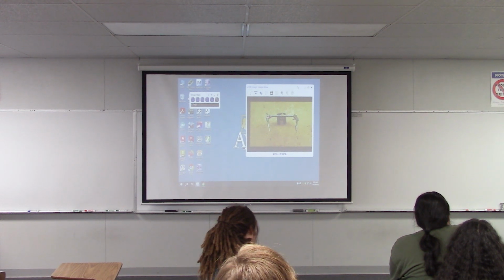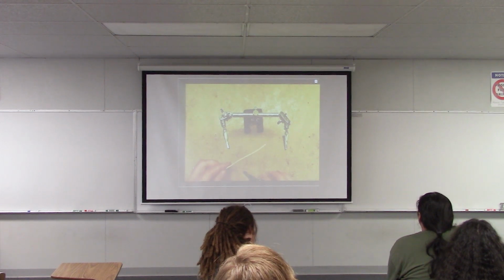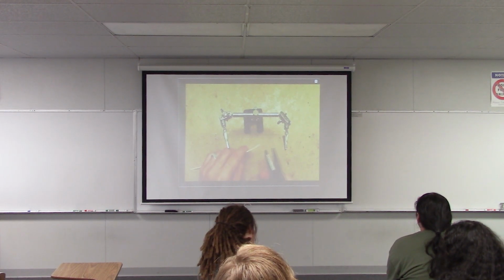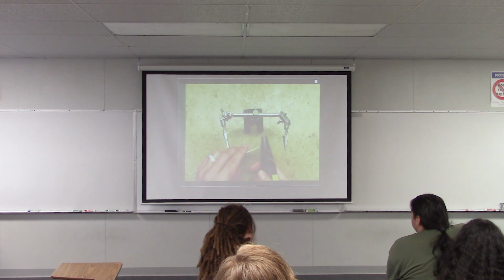And when you get the wire, it will have insulation around the outside. This insulation is this plasticky coating around the wire, and that keeps you from getting shocked if there's a voltage on the wire. So before you solder, you need to take this insulation off. And the way that we do that is with these wire strippers.